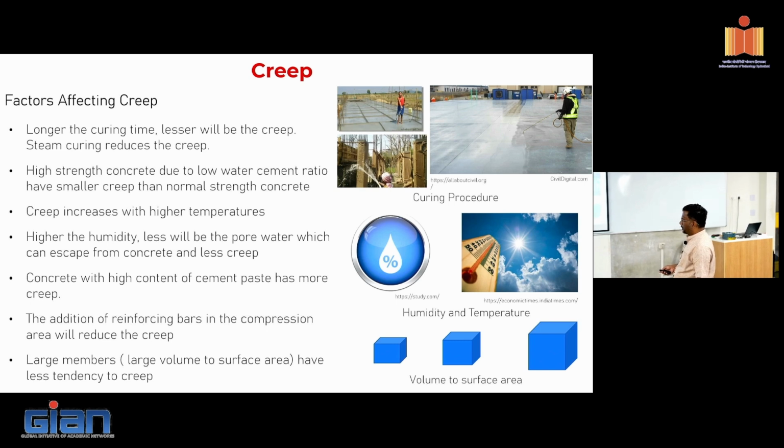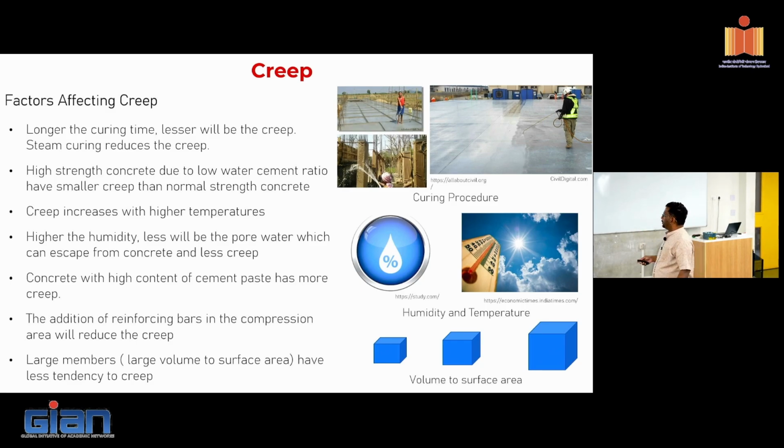So how does the code take this into account? That's where there is a factor called the notional size coefficient. That h0 is a factor that we typically use that accounts for this effect. Okay, the larger the surface area, the more creep you'll have.